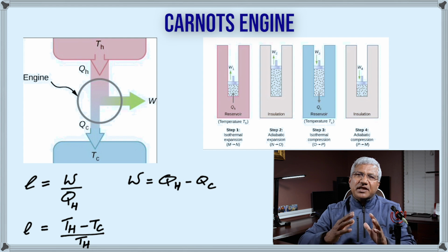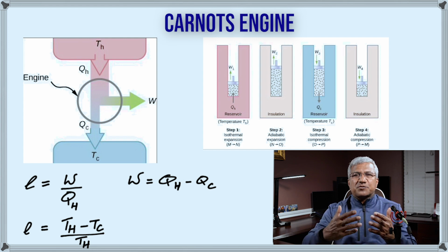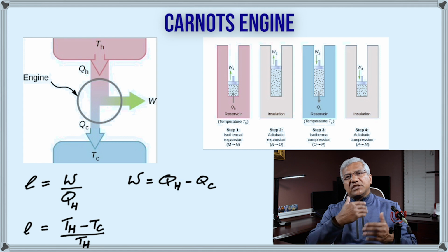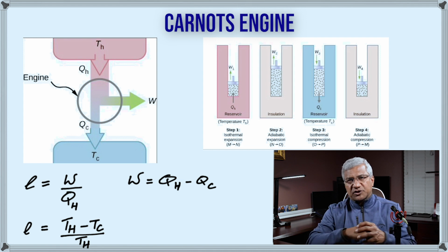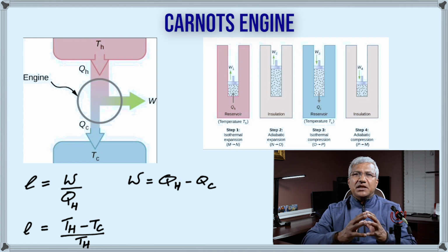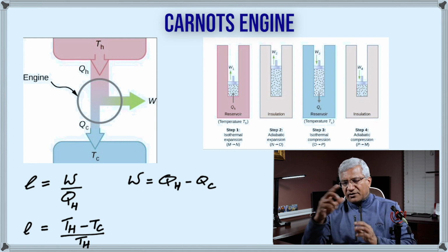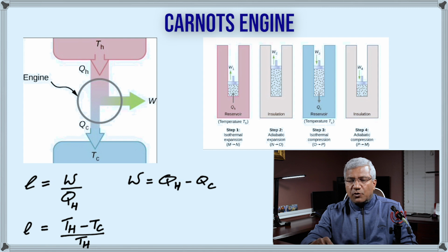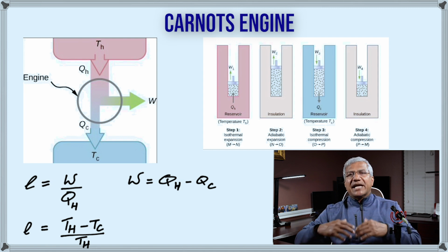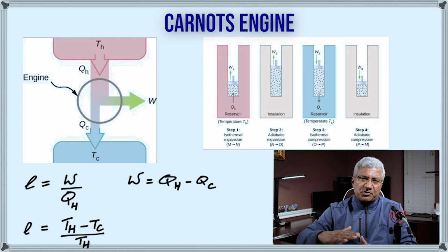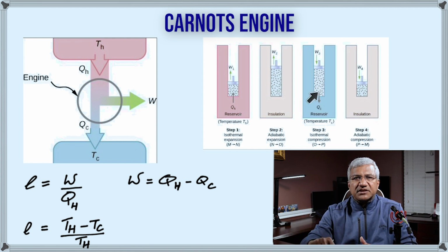So now the gas is still going to continue expanding because of the energy that it already absorbed in the previous process. But this is going to be an adiabatic expansion. Why? Because the system is not exchanging heat with its surroundings. In the third step, an external agency has to push the piston down, thereby compressing the gas isothermally.